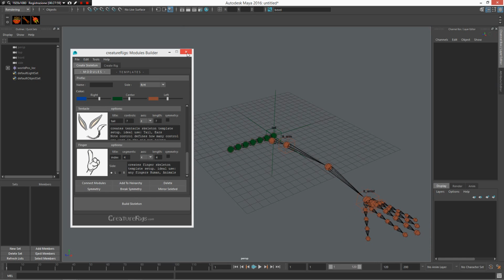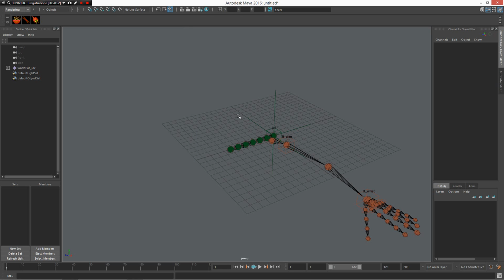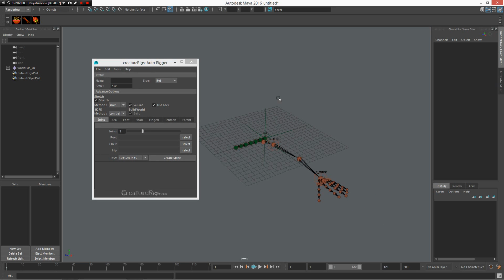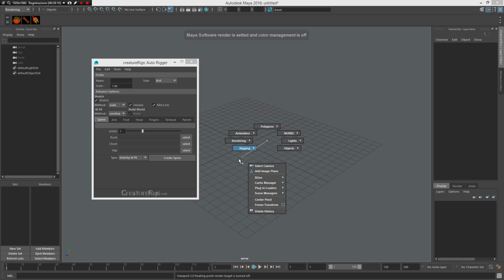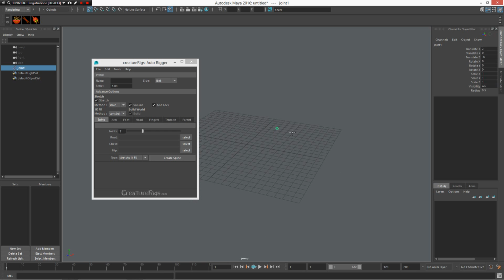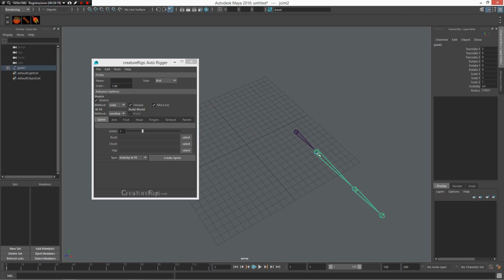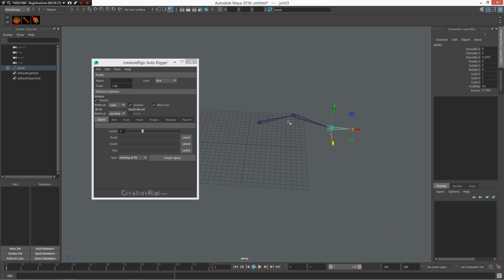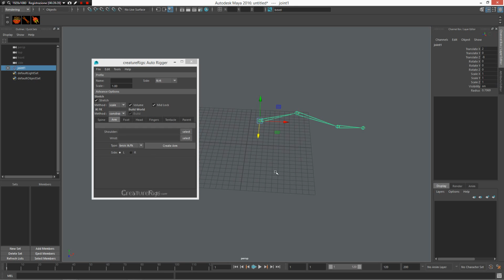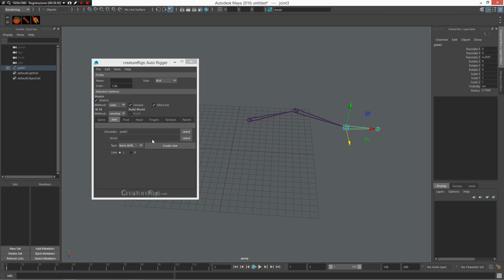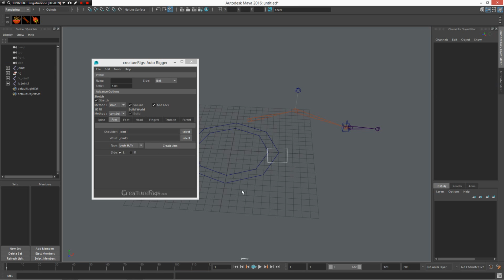And of course you can create a building skeleton, or the last tool: you can use your joint tool in auto rig mode. For example, I can create some joints with the joint tool, something similar to an arm, and now I want to rig this arm only by inputting the start, the shoulder and the wrist joint, and now I can create my arm left and right.